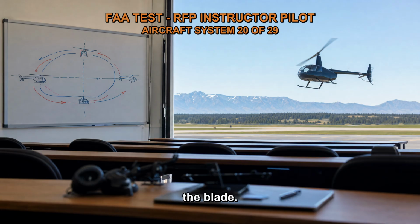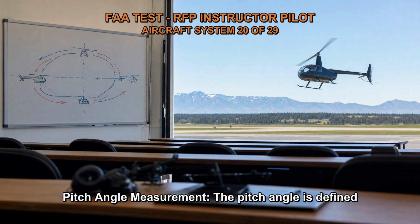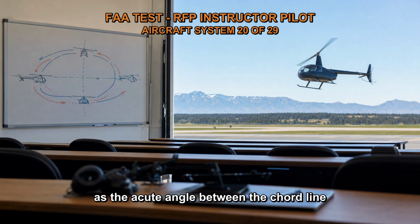Blade chord line: the chord line of a rotor blade is a straight line that connects the leading edge and the trailing edge of the blade. It is an imaginary line that represents the average shape of the blade cross-section. The chord line is typically straight, although it may have a slight curvature. Pitch angle measurement: the pitch angle is defined as the acute angle between the chord line of the rotor blade and the rotor plane of rotation.